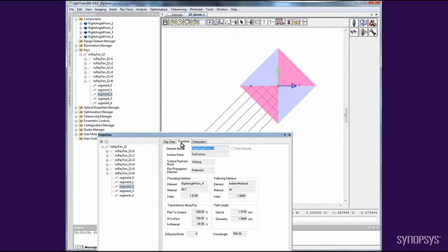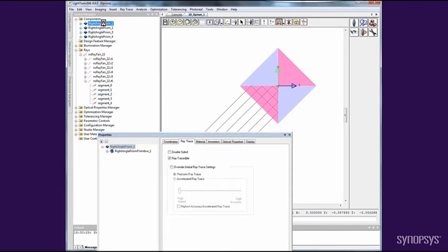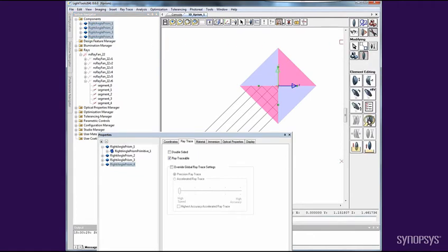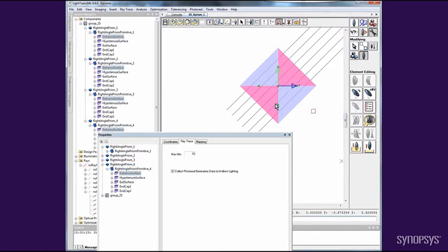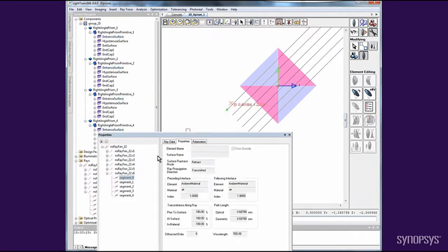The simplest way to identify adjacent surfaces that should be an optical contact is to use Auto-Declare Contacts. I'll start by selecting the four objects, then navigate to Modifying, Element Editing, Auto-Declare Contacts. You can see that this NS ray is now tracing through the prism as expected.